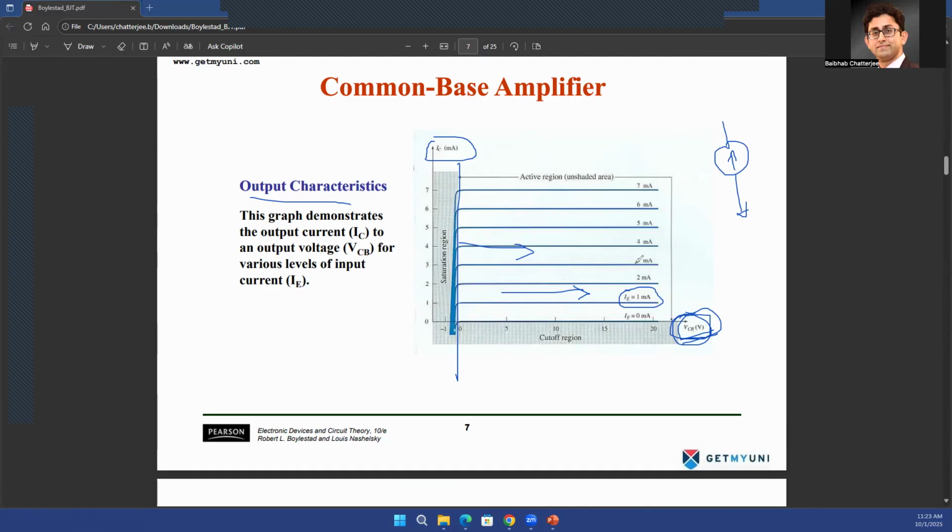And this is the first time you're seeing how that current source can actually be formed. We still didn't go into the theory, the physics yet. That we'll do from next lecture onward. But look at this entire region. The current at the output does not depend on the voltage at the output. It's a fixed quantity. It depends on something else. We'll come to that. But it's a fixed current source.